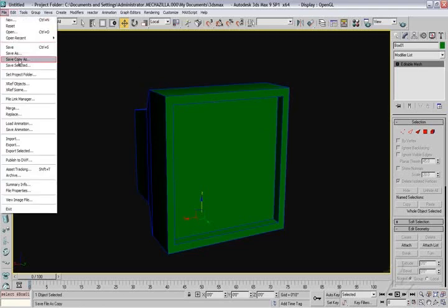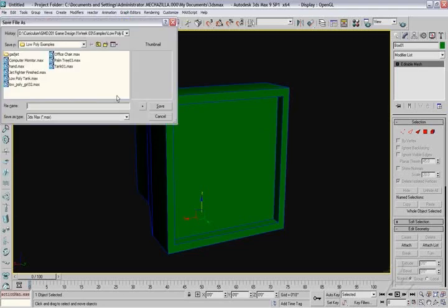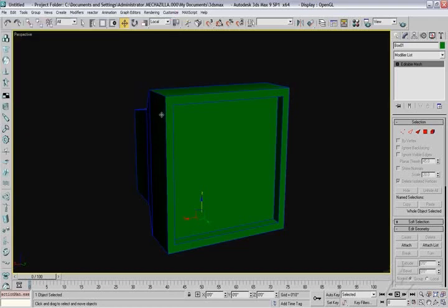At this point, again, you can choose File, Save As, and if you saved it with the list intact, you can save it as Computer Monitor. But before you actually click on the Save button here, click on the plus right next to the word Computer Monitor. This will allow you to create a new iteration of the file, meaning that you've got a fallback between the editable mesh and the editable mesh modifier. So there you go. That's how you can make a computer monitor, and that's your first introduction into box modeling.